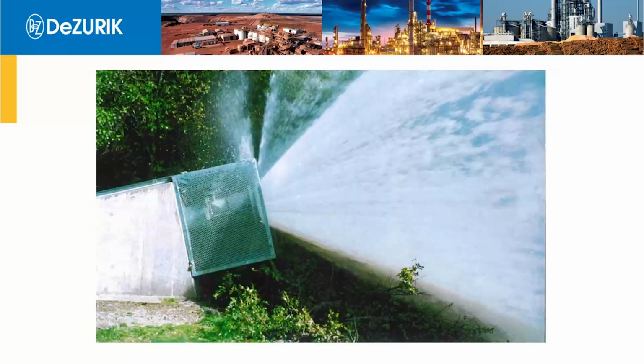So this is a fixed cone valve actually installed at a dam. That's probably about a 30 to 36-inch diameter fixed cone valve. You can see the discharge is pretty wide. It's a pretty wide field. So unless you have a tail race or a downstream area that's pretty wide open, it's going to create a big mist cloud, and that's actually a problem that a lot of operators, once they were installed, said, "Hey, I can't have this cloud. It's freezing up in the wintertime. Everything downstream is causing a problem. So what can you do?"